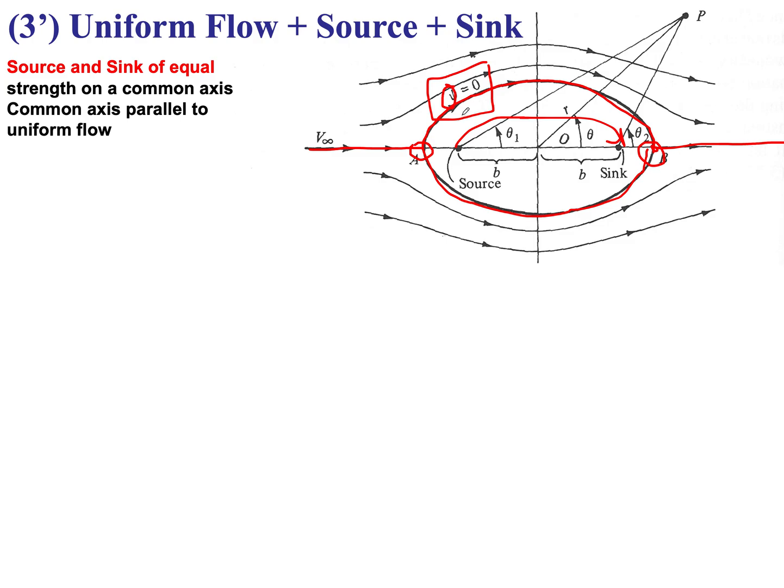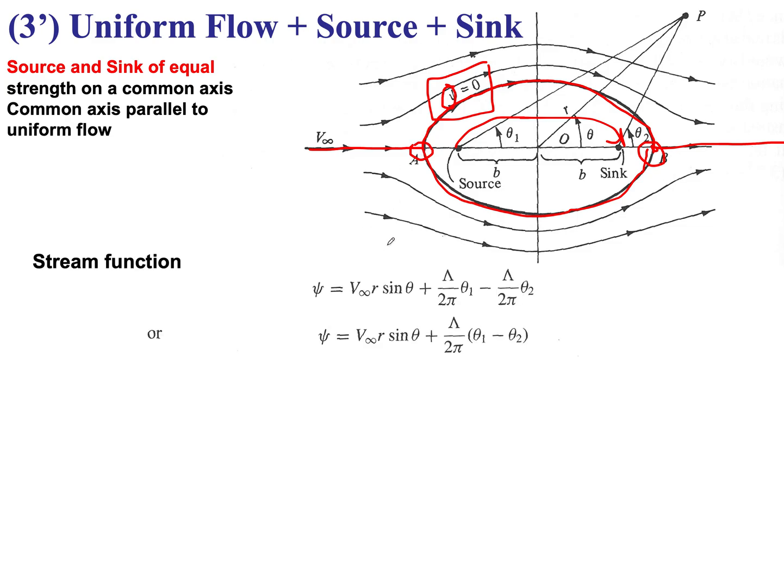We didn't find its shape, we only found its value, its magnitude. Then our next step is to find its shape, and to find its shape, you plug in the r and theta stagnation, or x stagnation, y stagnation, into the value of the stagnation function right here.